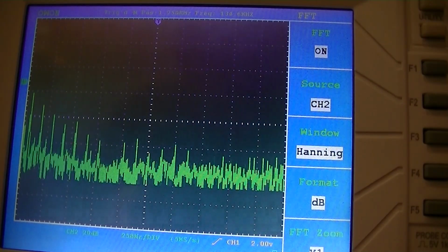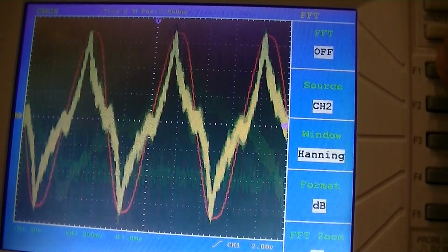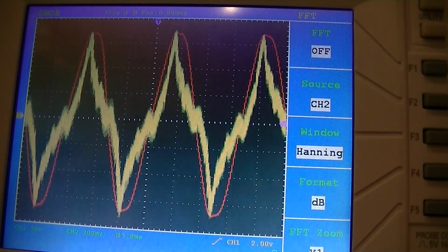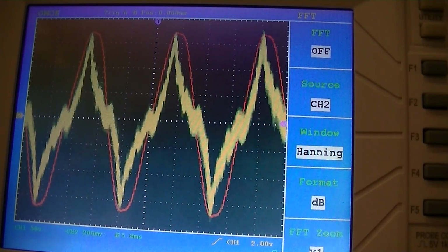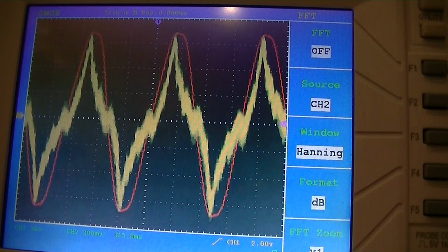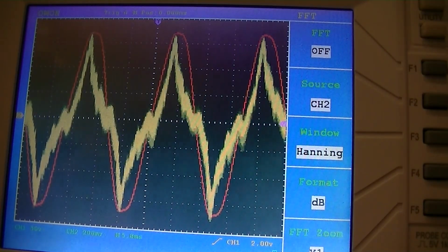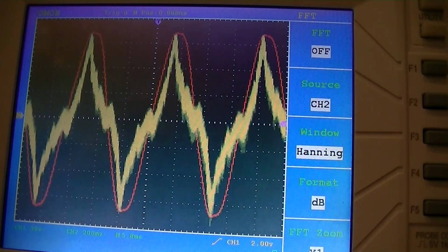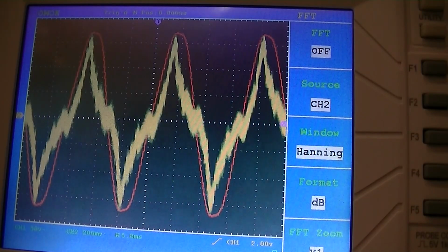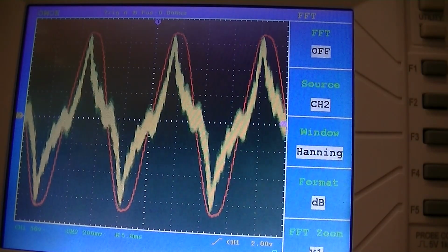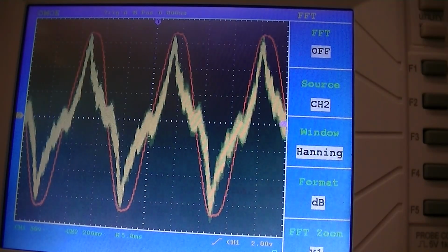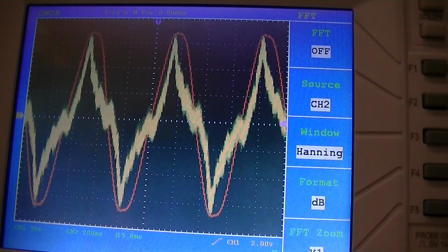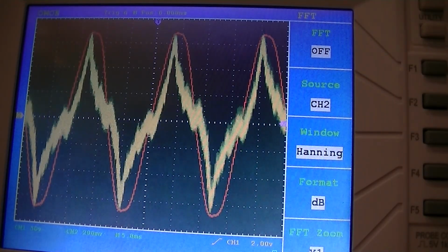And let's go back to the original waveforms, and that's what our waveforms look like. So I don't really see any change in the voltage waveform. All the changes with the capacitance occur on the grounding waveform. That is noticeable, and you can shift that waveform to the left or to the right, depending on whether you add capacitance to live 1 or live 2. But if you add it to both live 1 and live 2 the same amount, you actually retain the waveform. So that was my findings with a large amount of capacitance on the home electrical system.